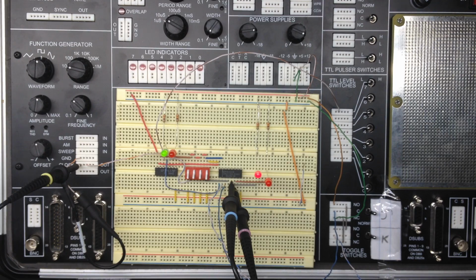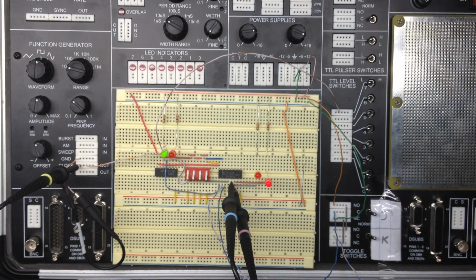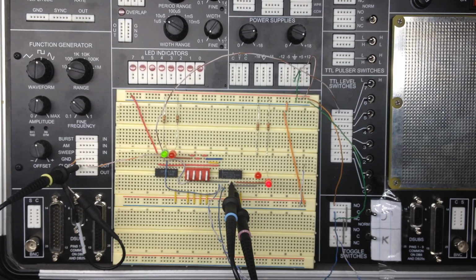The switch control that we're using for the inputs for the 74LS74 D input is TTL switch number 7 on the board that we're looking at. That would be here. We're going to use that to give our high or low signal to the D input, and then our high or low signal that's going to be going to the J and the K flip-flops are the toggle switches down at the bottom that are currently labeled J and K.